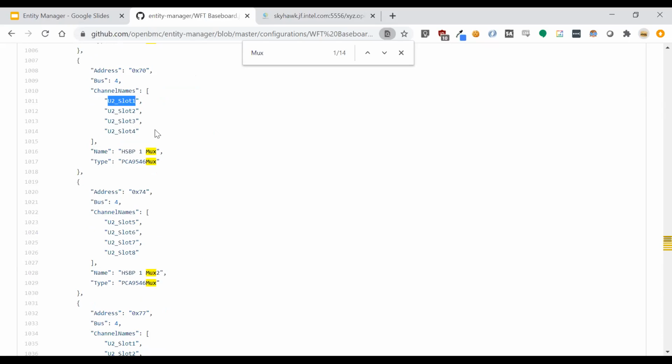I know it's not a fully baked answer, but that's the way that I think you could get there today. Yeah. So what we ended up doing is we stick the muxes in our device tree so that they have predictable enumerations, and then we use your math feature to compute buses relative to each other. Okay. Which got us by for now, but isn't useful on a variety of platforms.